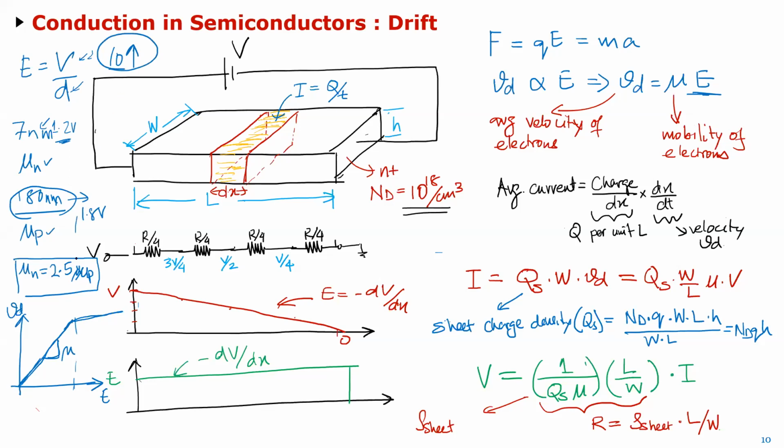Okay. So which means that you're in this region now where the mobilities are not as fast. So the mobility is hurting, or you have what's called hot electron effects and stuff like that. And the third thing is temperature. As the temperature goes higher and higher, the mobility also drops. So for higher temperature, the mobility will just start dropping.